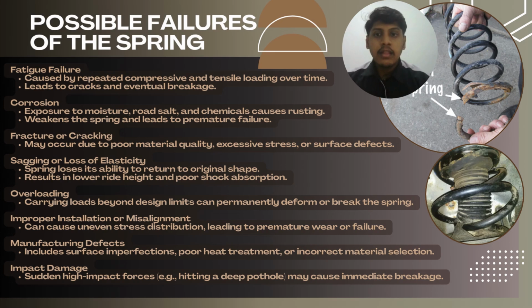Thirdly, the possible failure is fracture or cracking, which is due to poor material quality, excessive stress, or surface defects. Fourthly is sagging or loss of elasticity. The spring loses its ability to return to its original shape. It results in lower ride height and poor shock absorption. Fifthly, overloading. Carrying loads beyond design limits can permanently deform or break the spring.